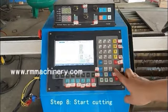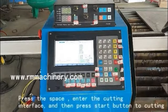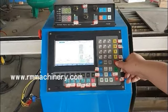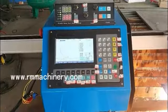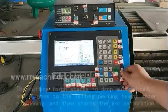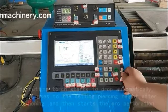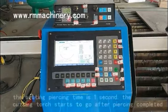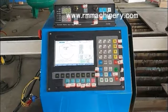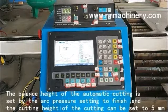Step 8, Start cutting. Press the space key to enter the cutting interface, and then press the Start button to cut. The cutting torch starts to drop automatically, and it rises to the setting piercing height after positioning, and then starts the arc perforation. The setting piercing time is 1 second. The cutting torch starts to move after piercing is completed. The balance height of the automatic cutting is set by the arc pressure setting, and the cutting height can be set to 5 mm.